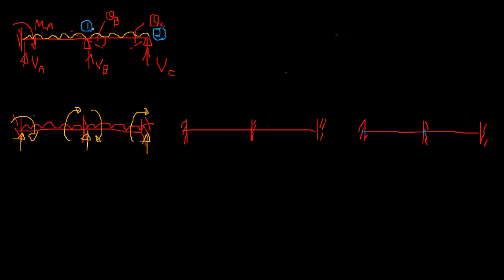So here, it's not like that. Here, we consider the equilibrium, right? So for equilibrium, you need to consider what corresponds to this displacement. If it is theta, theta corresponds always to the bending moment. If it is delta, the linear displacement, it corresponds to a force, right? Linear force, right? So since theta, you should consider the moment equilibrium at that joint. Since it is theta C, you should consider the moment equilibrium at this joint, right? So we are going to do that.